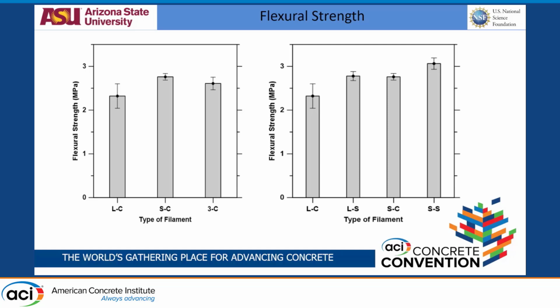Now that's in terms of when the filaments are curved. What happens if you stagger it? Just by staggering, if we see the linear conventional versus linear staggered, staggering the print itself made it possible to reach a strength similar to curving the filament. So that's also advantageous to your system. We get around a 20-30% increase, at least for this system. A different mix or a different printer might have a different percentage gain; we'll have to test those. But based on our mix and our print system, we got around a 20-30% increase with staggering of the layers too.